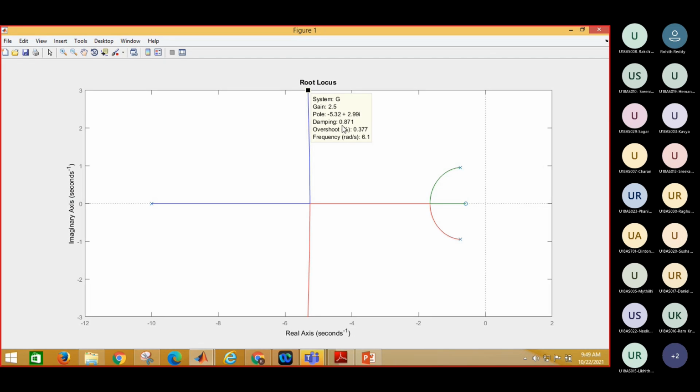If you couple with your outer loop, the closed outer loop has a tendency to reduce the damping. So if you initially select the inner loop with lower damping, when you incorporate the outer loop, it is reduced to an even lower damping value. If the damping is very low, then I have a peak overshoot. That's why we select a higher damping.